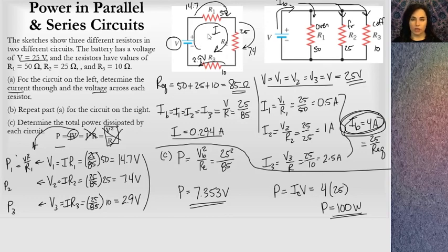It makes sense to add things in series. I'll just add something onto the circuit, but mindfully you can see that you're not going to get as much current going through each element. You might not get the current you need in order to create the heat in the oven you need, or to run your coffee maker, or to run the compressor in your refrigerator. All right, so that's why you connect in parallel rather than series when you're doing circuits in your house.